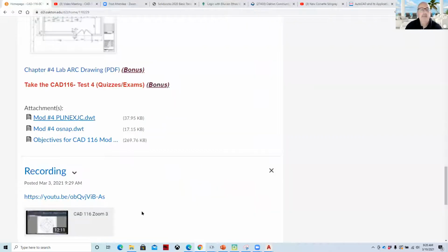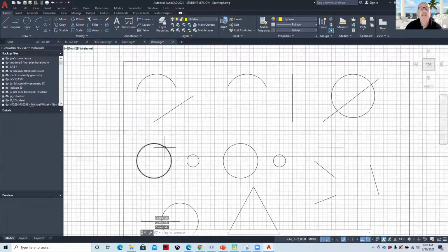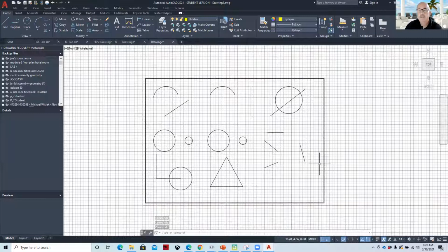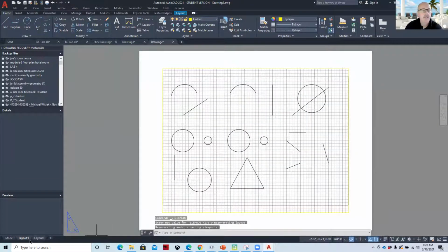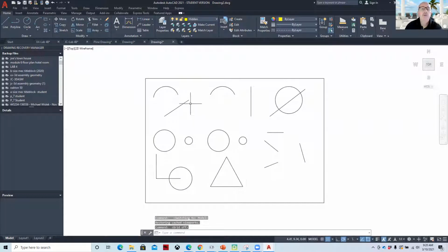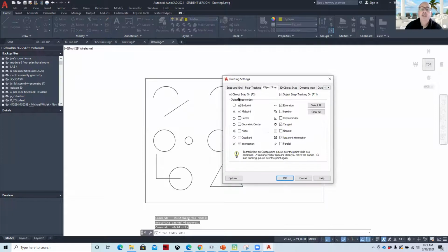And then if we come back to our main splash page, we have an additional general design called an Osnap drawing. Object snaps allow you to create these different geometries. Let me go back to model space here, where we can use this button right here. This is what's called an object snap. What they do is they're magnets. Whenever we're in a draw command and we're near an endpoint, it will magnetize to that geometry. And we'll get a glyph for that midpoint, which will look like a triangle, or a glyph for that intersection, which will look like an X.